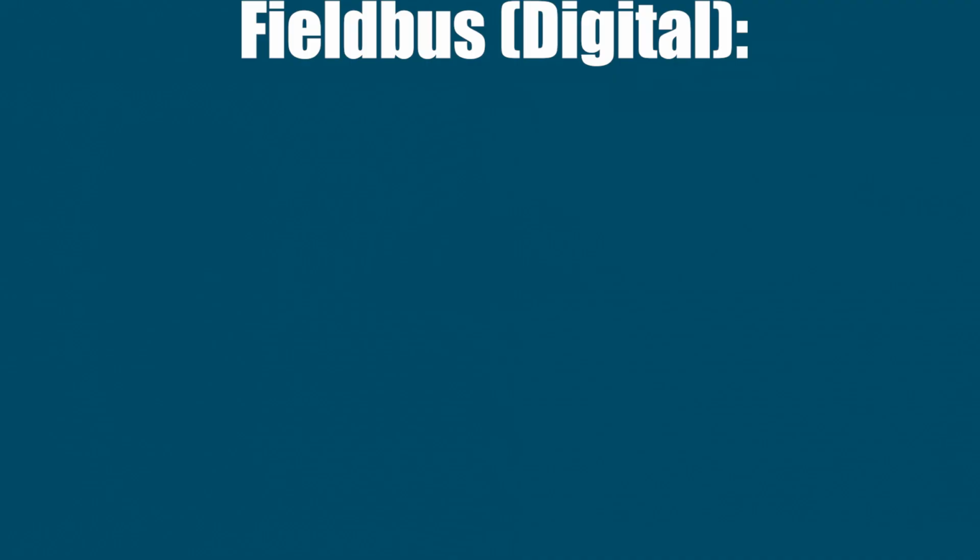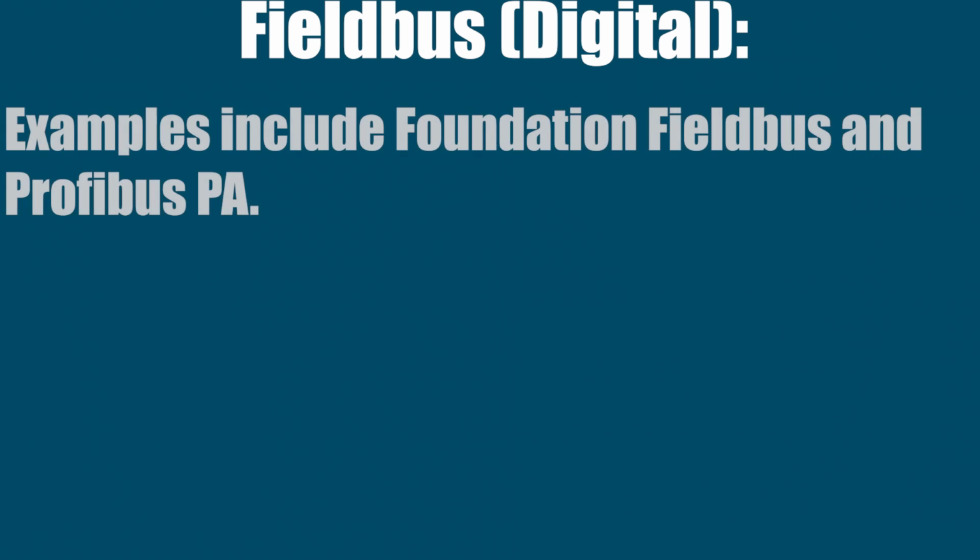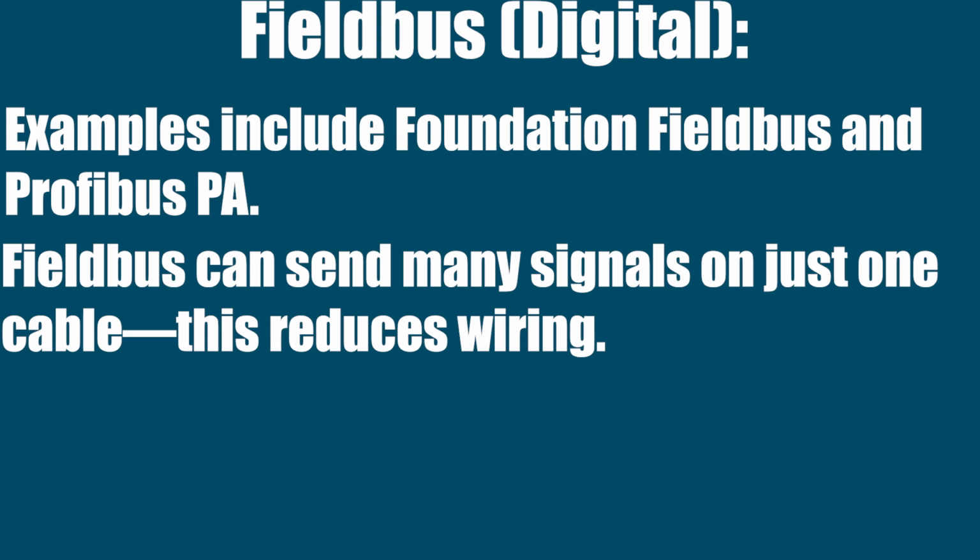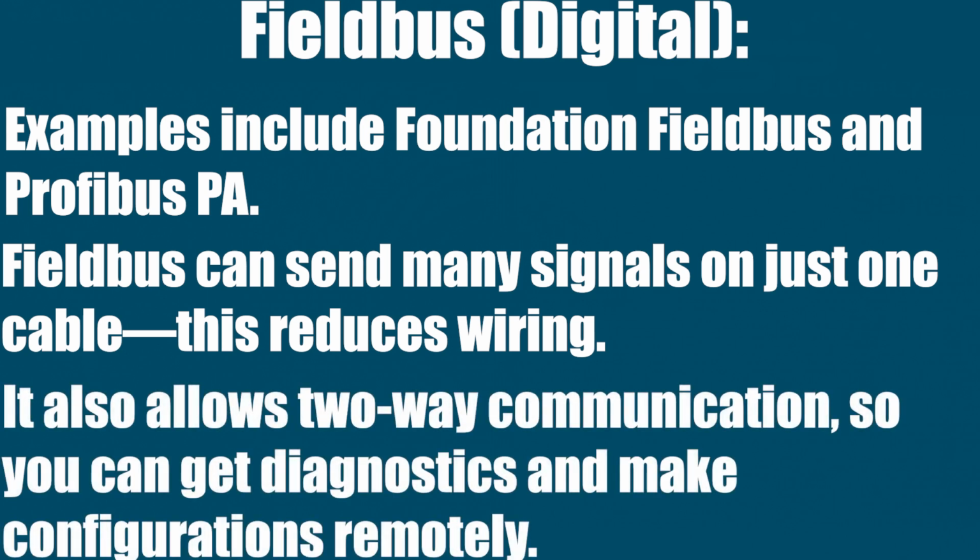Fieldbus, now we're going digital. Some examples are going to be Foundation Fieldbus and Profibus PA. Fieldbus can send many signals on just one cable. This is going to reduce wiring. It also allows two-way communication so you can get diagnostics and make configurations remotely.